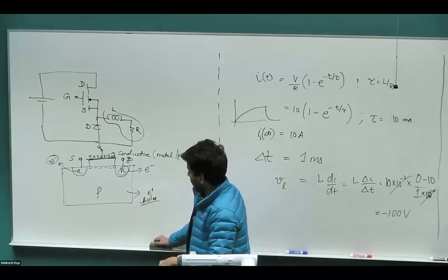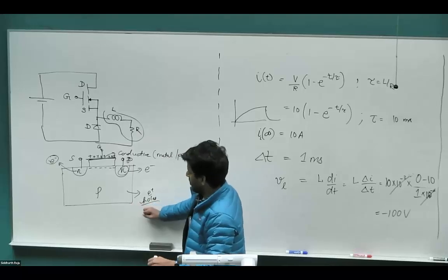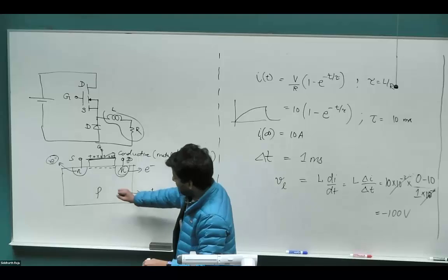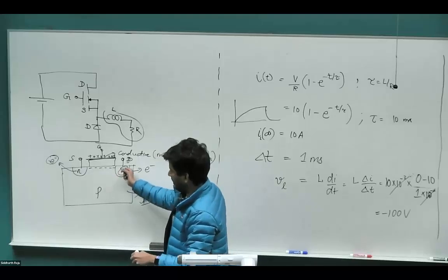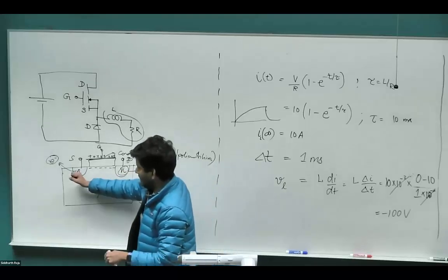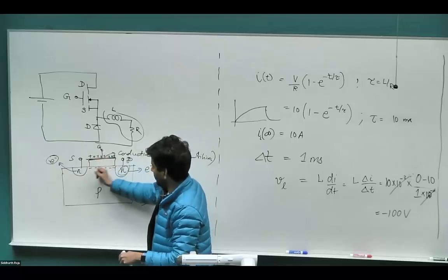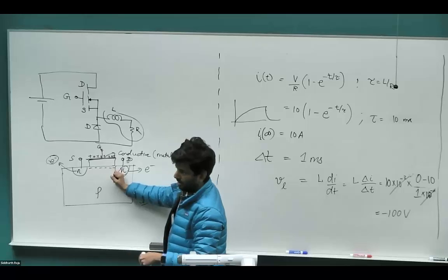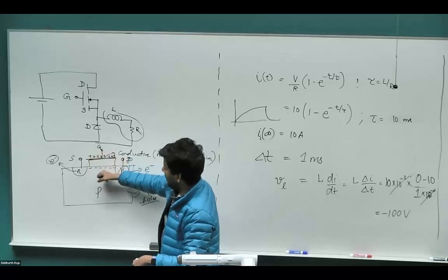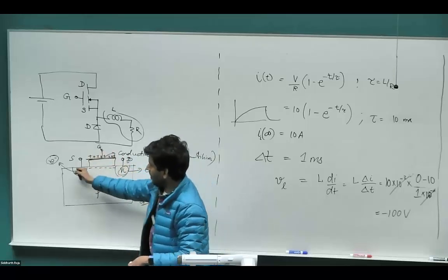Right? Again, if you don't understand the semiconductor part of it, don't worry about it. It's a separate course on its own. Too much to cover in this one. But this is the fundamental idea. So you have a bank of electrons available here, and when there is no gate voltage, these are two isolated regions, so there is no current flowing. But the moment you excite this gate, a channel is established, which can now conduct.